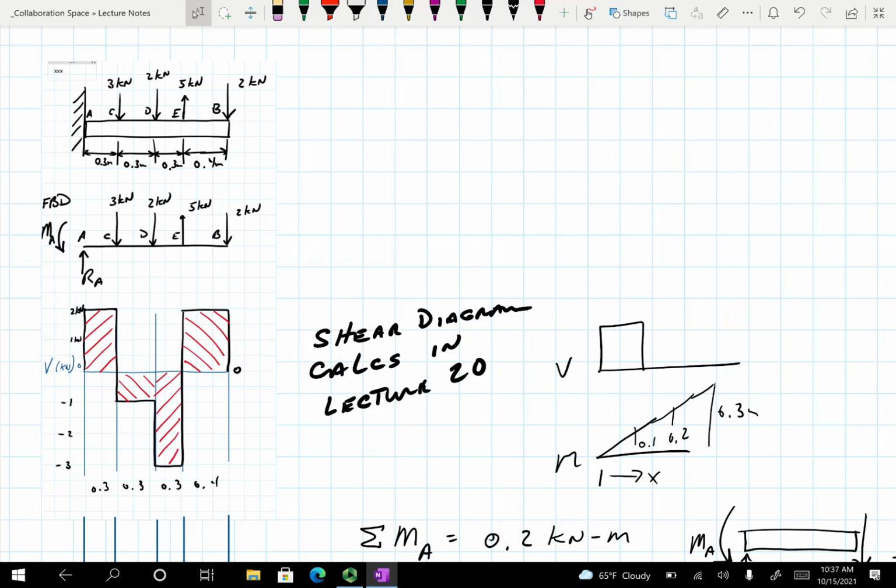So I put it into the equation down there, and then I went over to 0.2. So negative 0.2 kilonewtons plus the 2 kilonewtons times the 0.2 meters would be what number now? What's the area of the 2 kilonewton force moved left 0.2 meters?